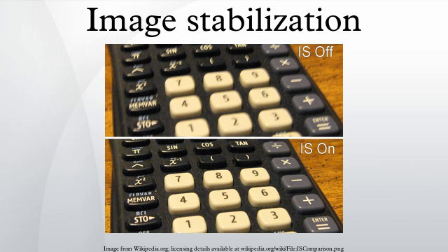Orthogonal transverse CCD, used in astronomy. An orthogonal transverse CCD actually shifts the image within the CCD itself while the image is being captured, based on analysis of the apparent motion of bright stars. This is a rare example of digital stabilization for still pictures. An example of this is in the upcoming gigapixel telescope Pan-STARRS being constructed in Hawaii.